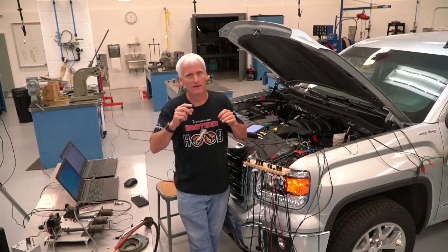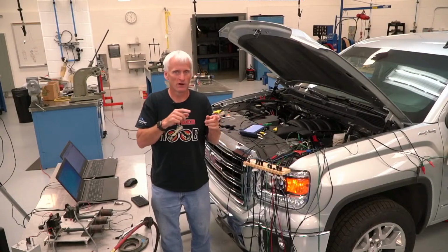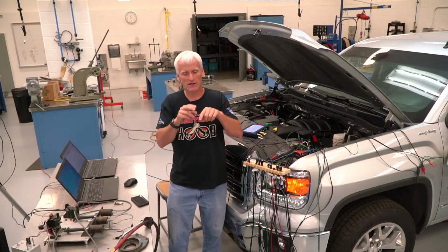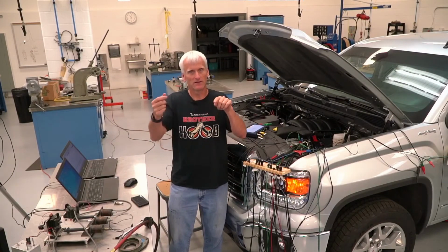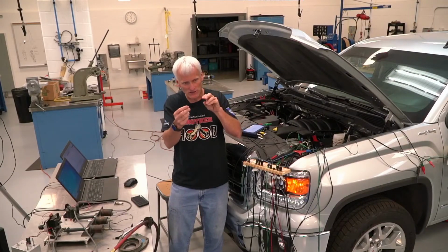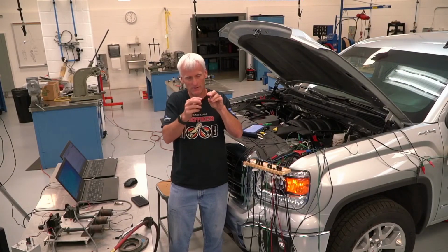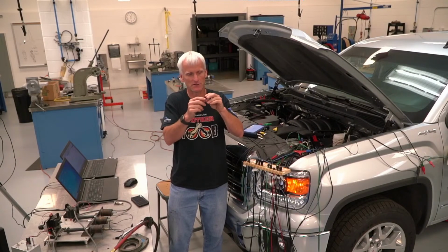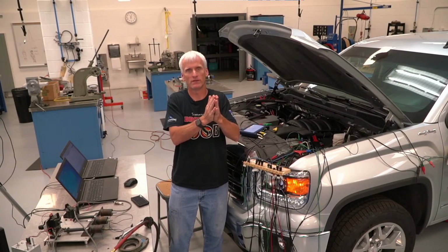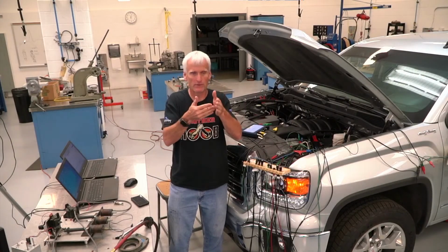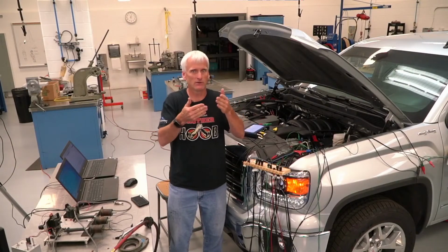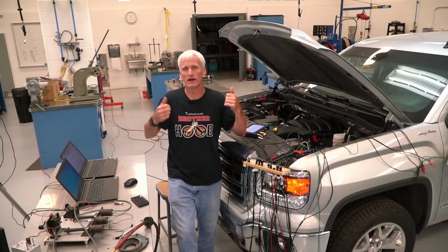So it needed the hydrogen from the hydrocarbon to complete the chemical reaction on the tip of the O2 sensor, and that allowed oxygen to pump through the ions, the zirconia of the sensor, and combine with the H from the propane or the acetylene or whatever I was pumping in there, and then boom, and outputted a voltage.